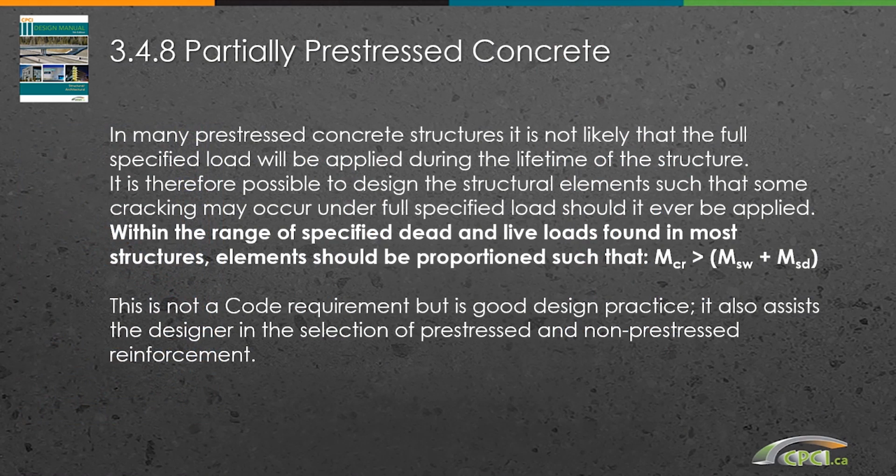Now we come to the partially pre-stressed concrete as a concept. Sometimes we know that the live load is not happening in real life. Therefore, it's not a bad idea to assume that the pre-stress section, under full load, if it ever occurs, can show a little bit of extra stress over and above the allowed by code for the tensile face of the section at the bottom.